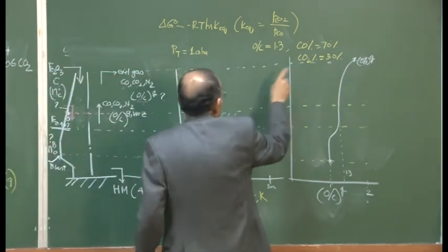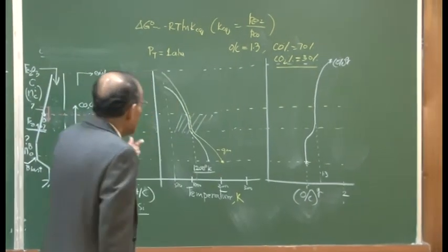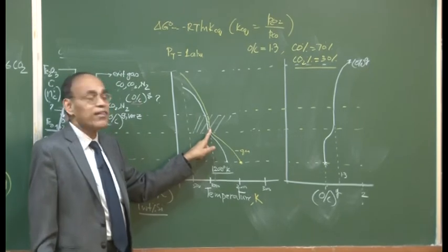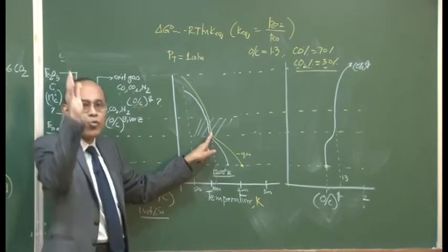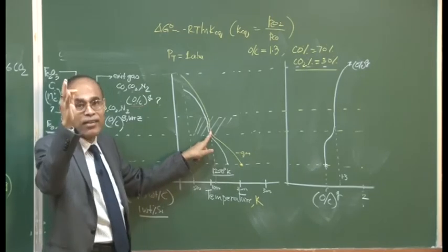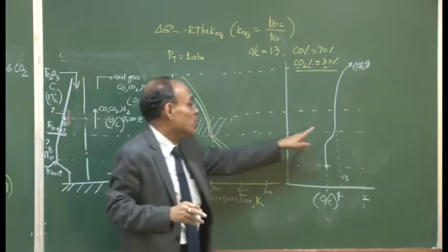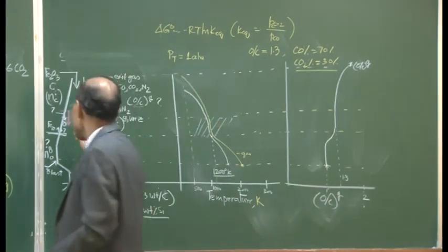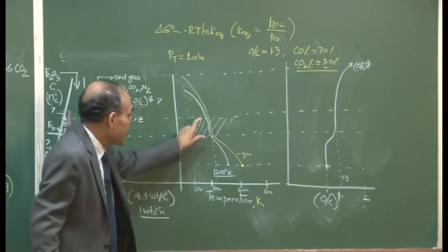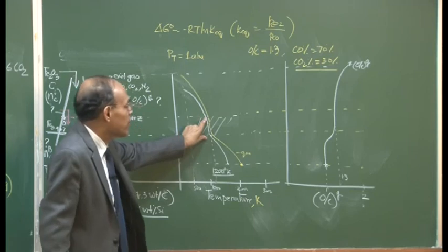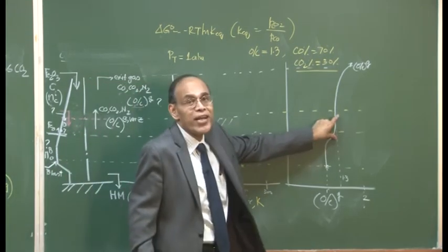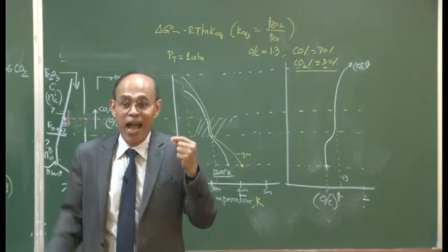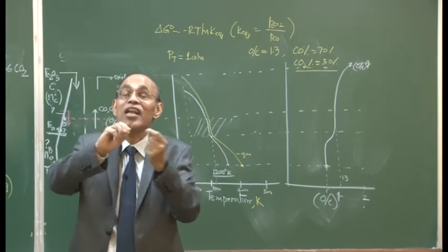Based on that, if we assume the total pressure to be equal to 1, this figure essentially suggests that at 1200 degree centigrade, when the wustite reduction reaction is taking place, it is virtually at thermodynamic or chemical equilibrium, and this is manifested by a constant O by C ratio, as I have indicated in this figure. This characteristic of a furnace, that you have a stable region of constant temperature and a stable region of constant O by C ratio, is called the chemical and thermal reserve zone of a blast furnace. And this is a characteristic of all modern large blast furnaces.